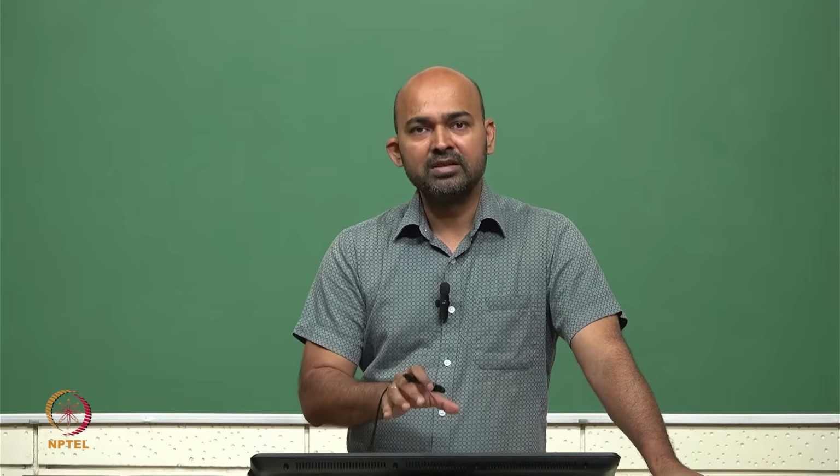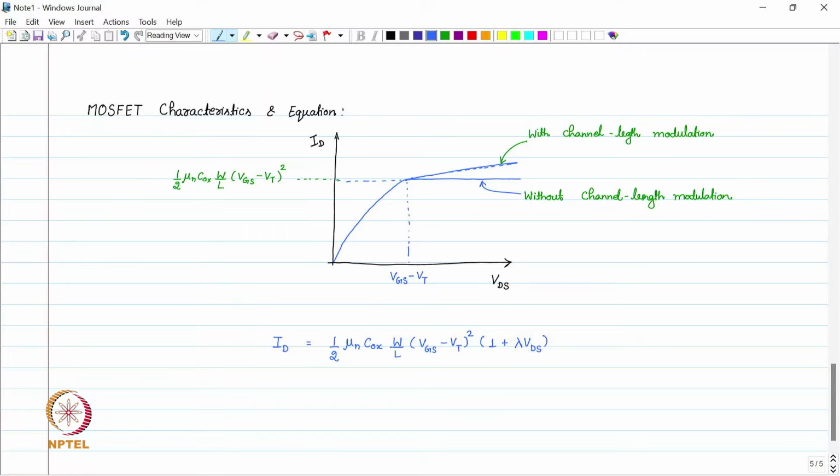These characteristics are generally measured on silicon once we fabricate the device. Once we have these characteristics like ID versus VDS, ID versus VGS, and for different values of VDS and VGS, we take these values and try to make equations for these graphs so that we can use a computer to solve these equations.